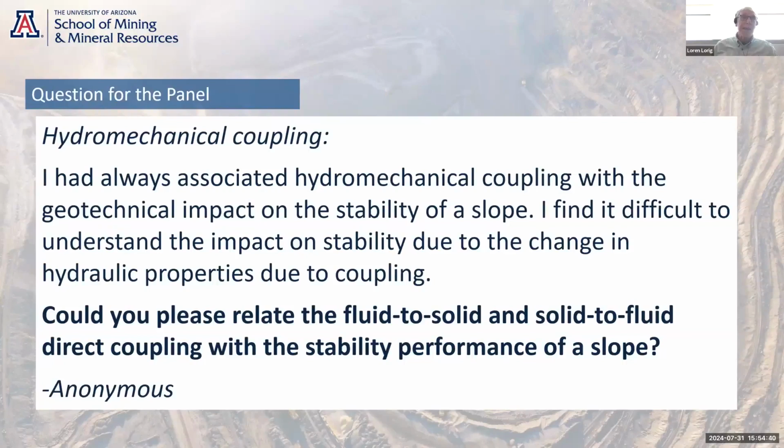We very seldom have what would be considered a fully hydromechanically coupled model where we're looking at changes in permeability, changes in pore pressure, changes in mechanical stresses. But what we try and do is figure out which of those is the primary behavior and kind of focus on that and make the assumption that the other ones are of secondary importance.